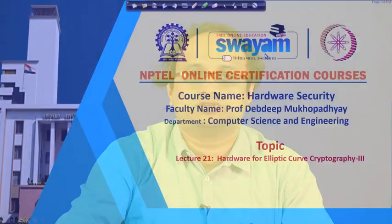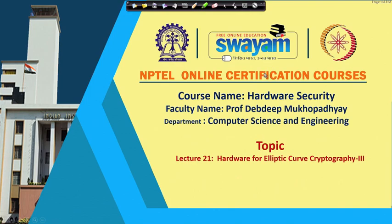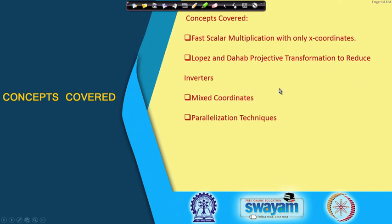So, welcome to this class on hardware security. Today we shall be continuing with our discussions on elliptic curve crypto systems and their implementations. We were discussing in the last class about Montgomery's technique of scalar multiplication. In particular, today we will be discussing how to perform a fast scalar multiplication with only one coordinate, that is only x coordinates. So, we basically do not need the y coordinates, and that is a very efficient way of doing this operation.